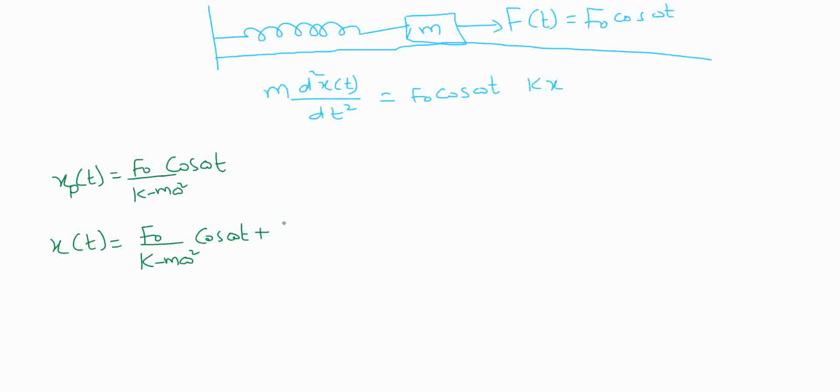So the xn will be in the form of c1 cos omega t plus c2 sin omega t. This omega is different from this omega. This is the forced response frequency, and this is the natural frequency. So please see the difference, omega n here. This omega is the forced term given, and this omega n is equal to under root k by m.